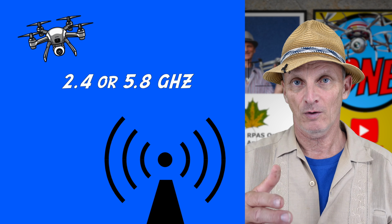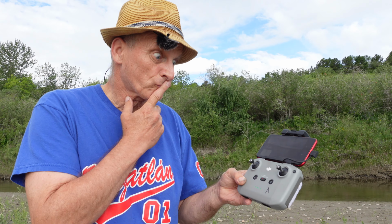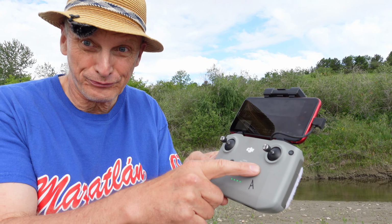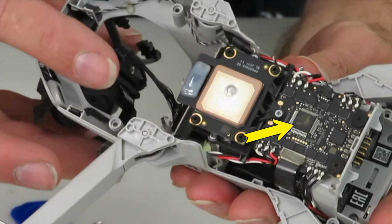It works well, but nothing is foolproof. If you lose connection, try pointing your antenna toward the drone. If it doesn't work, try briefly turning off and then restarting the controller. And if nothing works, your return to home function should kick in, assuming it was set up correctly. All of this communication is handled by a transceiver, which relays signals between the controller and the drone's brain, the Flight Control Module, FCM for short.